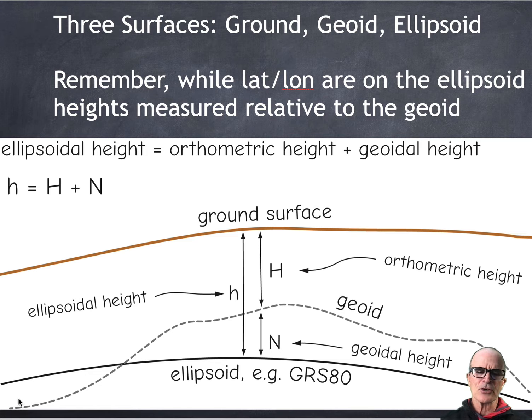Why do we have this geoid? The way to think of this geoid is it's kind of like our mean sea level we used to use as our base, and it's extended into the various continents, sort of under or over the continents as a reference height. A geoid is defined as a surface where the pull of gravity is at a specified constant, and each country can specify a different constant for their geoid.